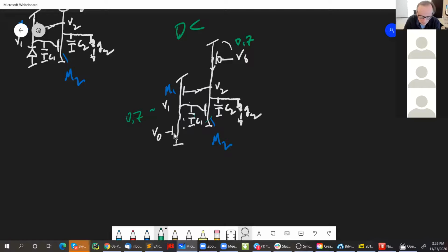What about V2? What must V2 be? Let's be explicit here and set this input voltage equal to 0.4 volts, right? So by this reasoning, what must V2 be? The V0 is 0.4 volts. Well, if V0 is 0.4 volts, this transistor M0 here is conducting 0.4 volts worth of current. So that must flow through M1 also, correct?